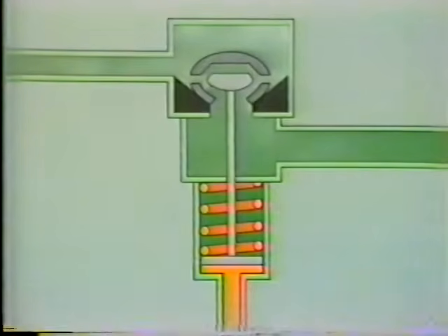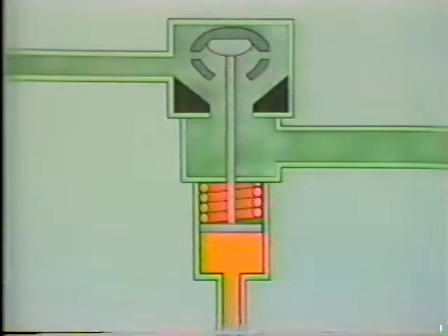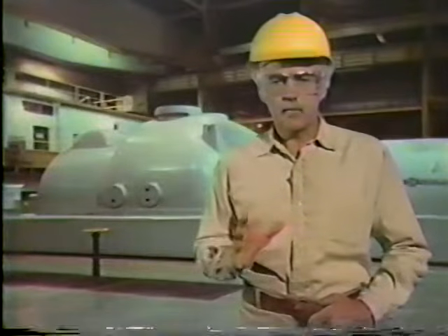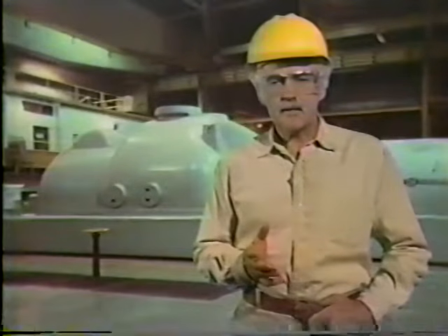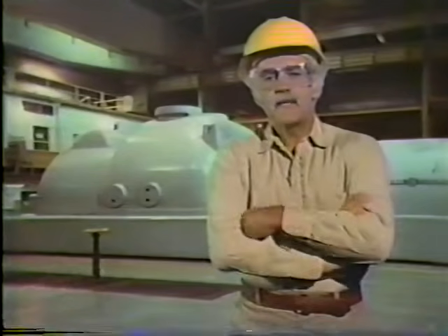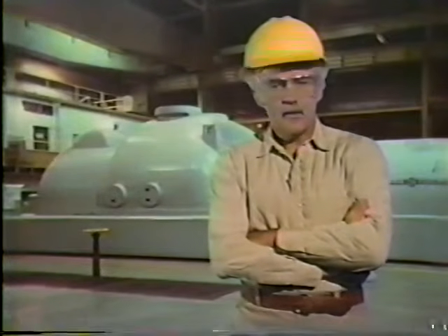startup. When the turbine is up to speed, the bypass valve disc is raised more, lifting the main stop valve disc off its seat. In addition, the other main stop valves are also open. In this position, there is a full flow of steam towards the turbine. When the main stop valves are fully open, the flow of steam into the turbine is regulated by the control valves. The turbine control valves have the job of controlling either the turbine's speed or the turbine's power output.